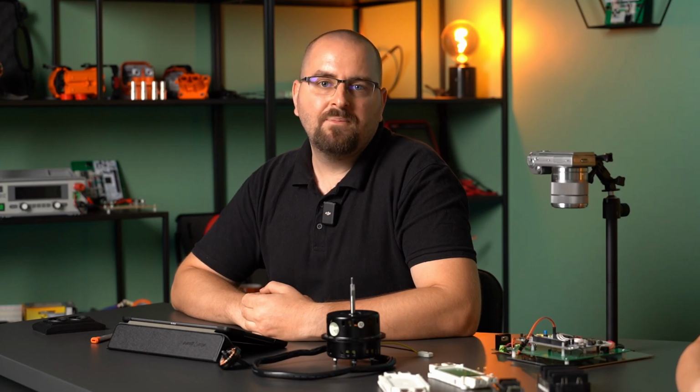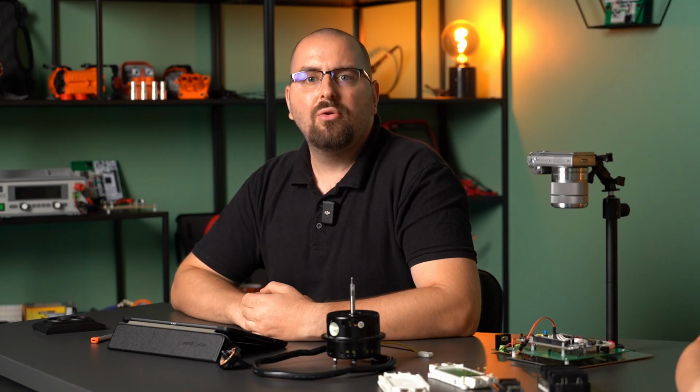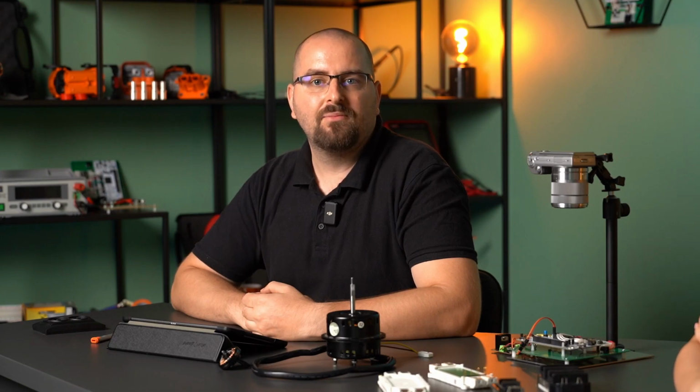A further disadvantage of brushed motors is that the rotor can heat up considerably due to the current flowing through it, and cooling this can be difficult in thin air, meaning in low air pressure. Examples of these problems include the space industry, where engineers have had to develop a DC motor that can be used in the vacuum of space, so it doesn't overheat, and one that can be used in oxygen-rich environments, so one that doesn't cause sparking, used for mixing the oxygen tanks of spacecraft, for example, and without pollution, so without the fine dust produced by carbon brushes.